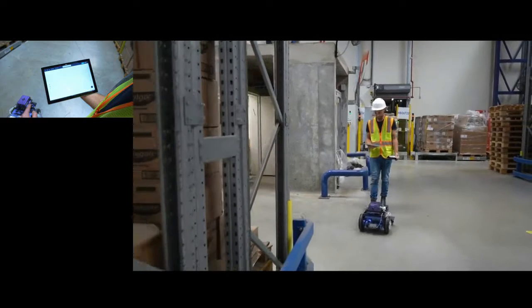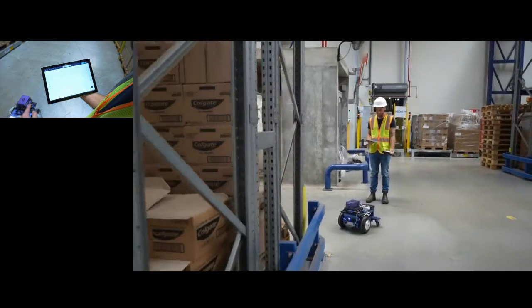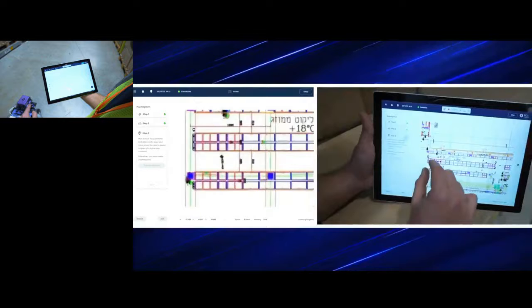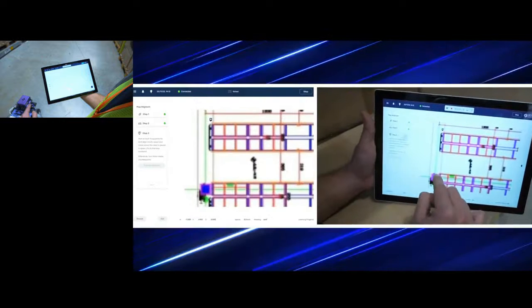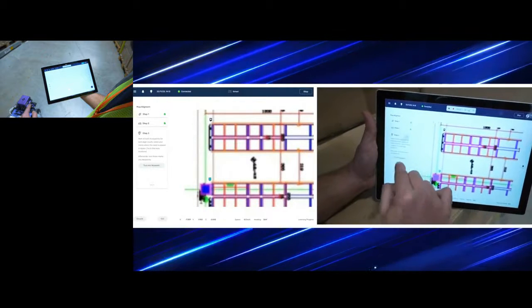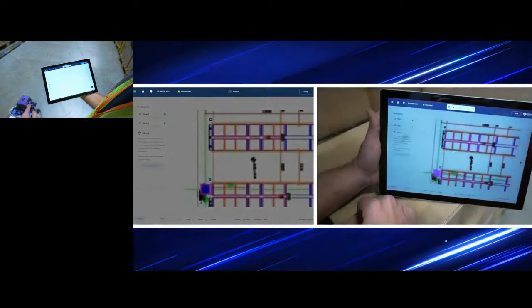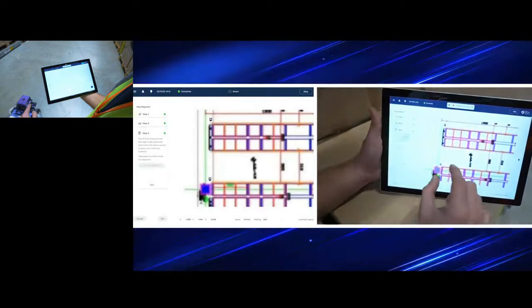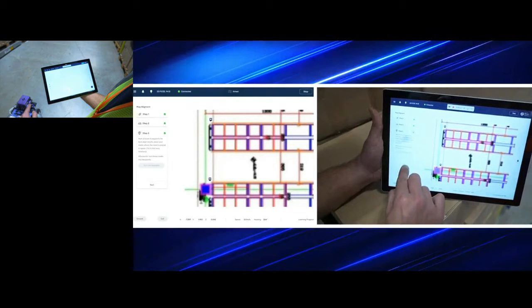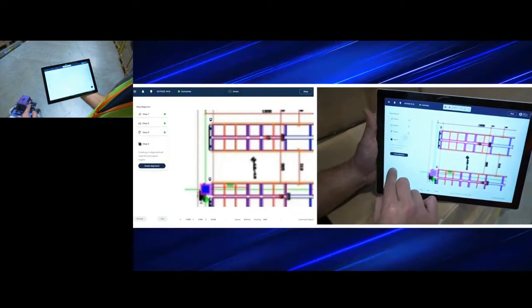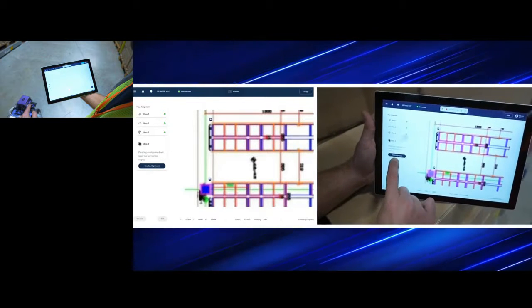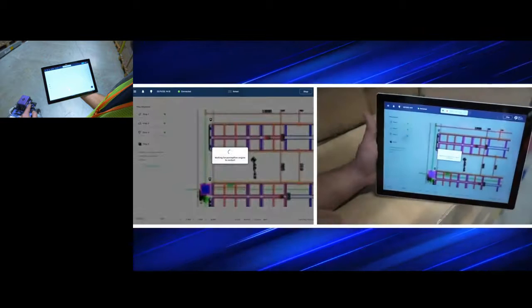He will stop for just a second and tell the RGo Perception Engine, this is where I am in the real world. And you can see here a very intuitive UI, easy operation. You just click the button, say, I'm here, and then continue to the next point. The minimum required is 4 points to do an accurate translation.